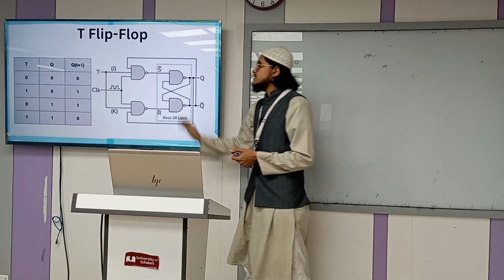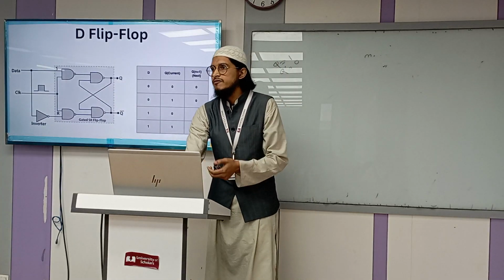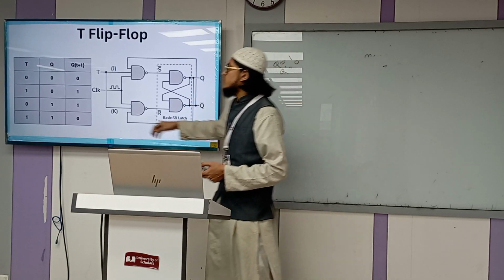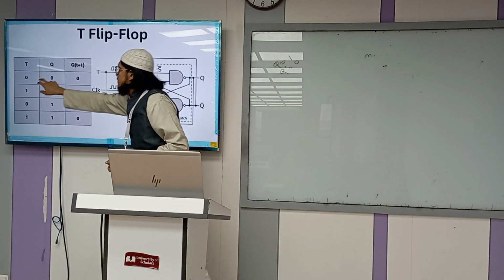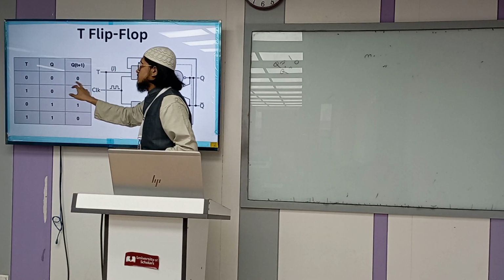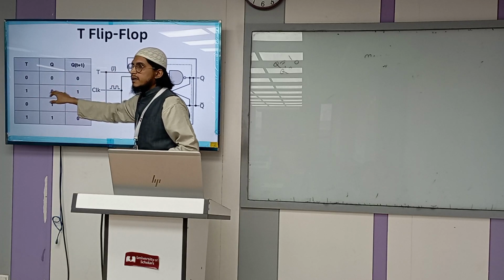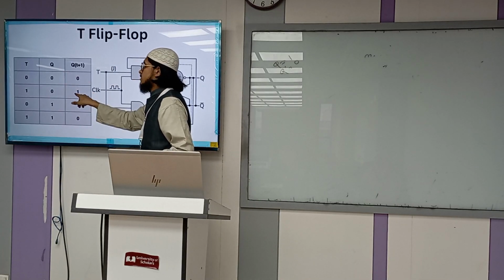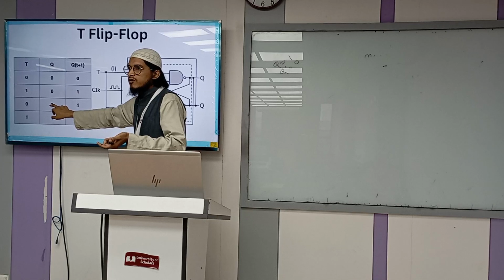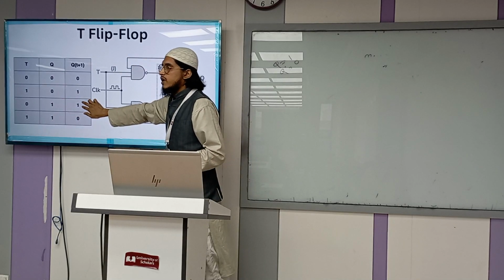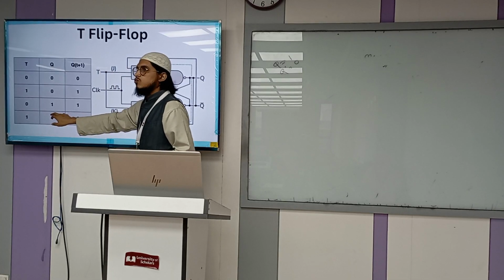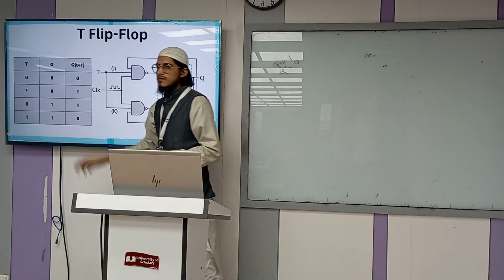So here is a T flip-flop, which is actually the reverse form of the D flip-flop. It just triggers or inverts the output. Here we have T 0, Q 0, and for 0 we got 0. For 1, here we have 1, but it triggered it, so 0 becomes 1. We have 0 and our past output is 0. That's the hold condition. For 1 we know it's going to trigger it. So my past output was 1 and it triggered it and it becomes 0.